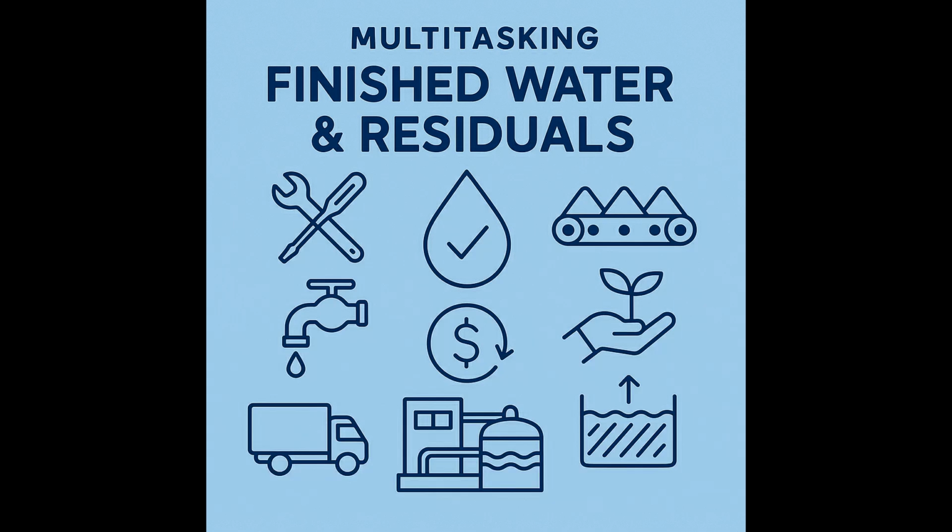And the advantages? Lower energy use is a big one, much lower than centrifuges. They're also quieter, generally simpler mechanically, easy to automate, and often require less maintenance. They can also tolerate varying flows pretty well. It's a technology that's really gained popularity, especially for small to medium plants.